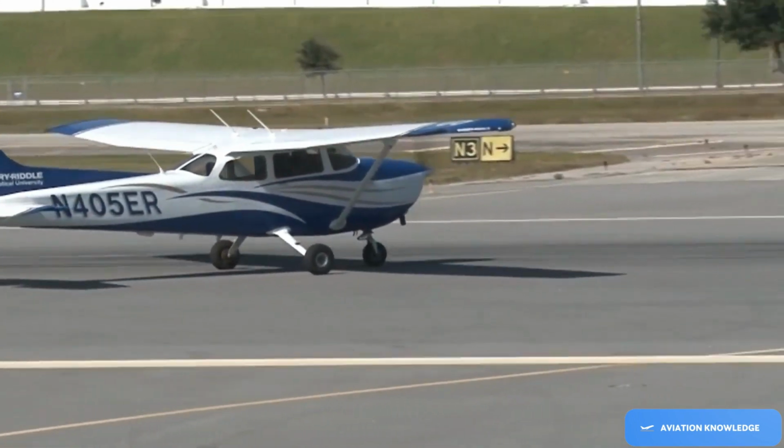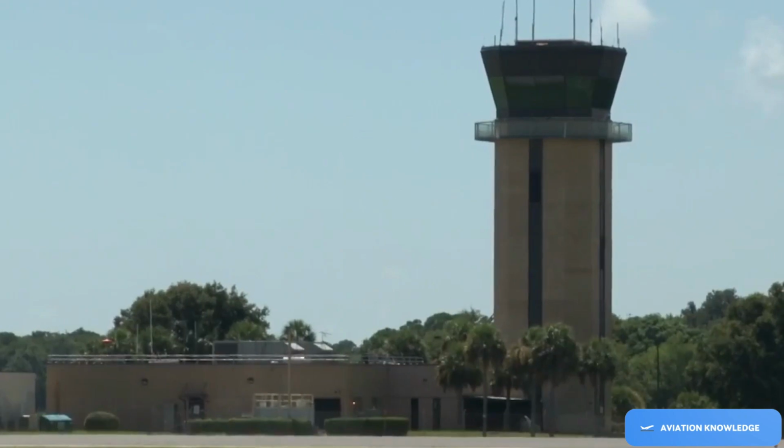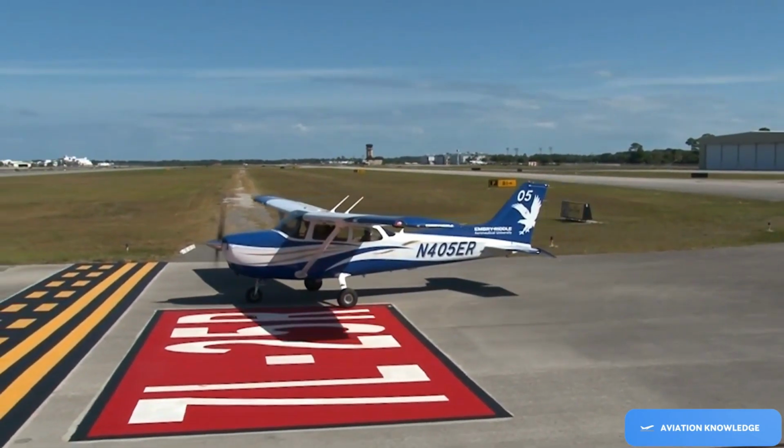Secondly, the pilot should also confirm they are entering the correct runway. Verbally brief what runway you are entering, and confirm with your instructor which direction you will be taking off in. If you're at a towered airport, make sure your runway is in agreement with the clearance given by ATC.